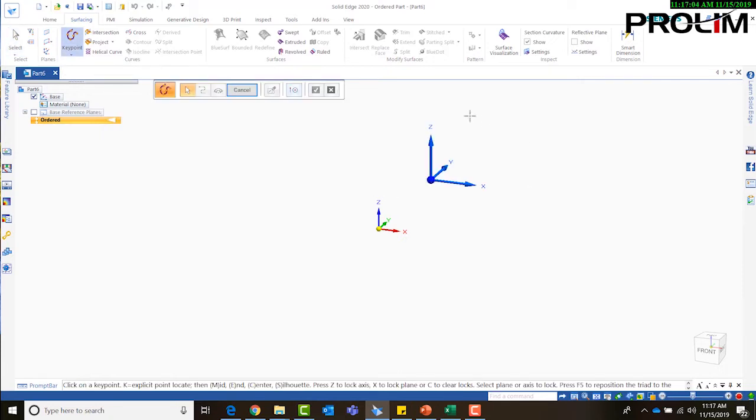And we're going to get this XYZ axis right here. This is not our origin. This is just reference for creating our key point curve. The first thing I'm going to do is select the origin point. This is what I want to make my first point. Right now I can just drag my cursor out anywhere and my line will follow. If I click on a space here, it'll create another node.